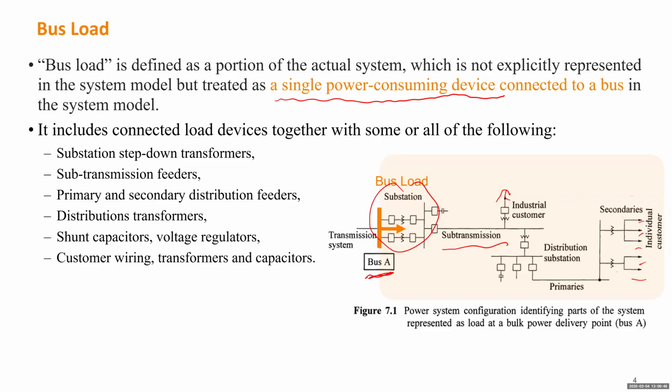So when we talk about voltage control and voltage stability, we'll use one example to show you that either just aggregating everything in this area by a very simple element, compared to the original topology of the system considering transformers and controllers, the result can be very different. Sometimes you may want to keep the transformer and voltage controller in the model. You don't want to reduce those by simply a load device.